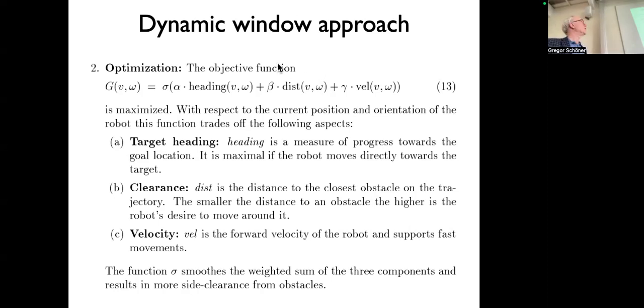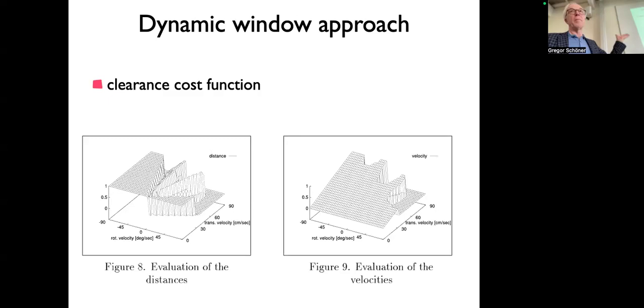And by having a parameter in front of each, you can weigh them differently. Like, we would say the obstacle term has to have priority, so make this larger, and this one maybe smaller, and so on. So in that sense, it's an arbitrary dimension that just helps you compare the different contributions, and within every contribution, you're maximizing something.